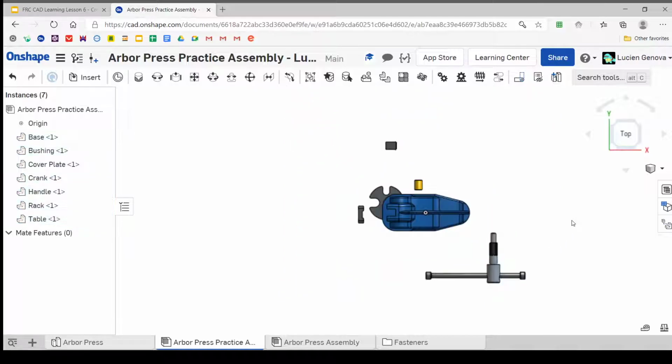So we'll rotate this. Now, in Onshape, you can highlight two different ways, right? If you do yellow highlight, which is to the left, it'll select anything that's even partially contained in the highlight box, right? So if you select this and then even just a little bit of this, it'll select them all. If you do blue highlight, it'll select only something that's completely contained in the highlight window. So only this box here. And that's really useful, right? If you're trying to highlight only these things, but you can't really fit that, then it'll only highlight these things.